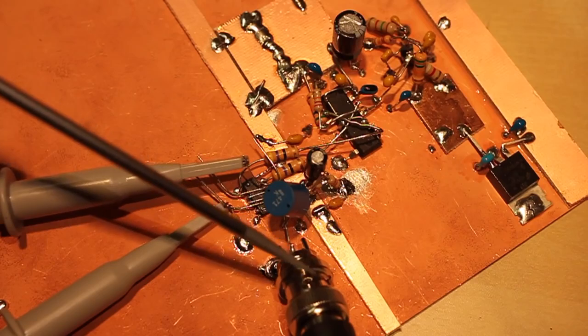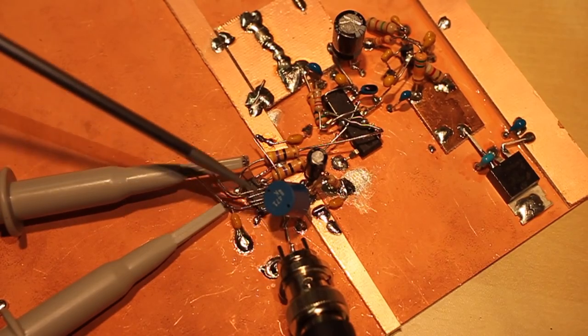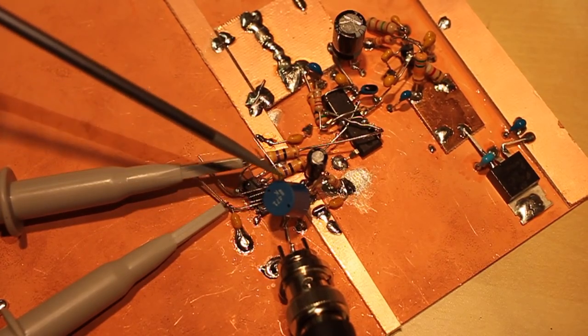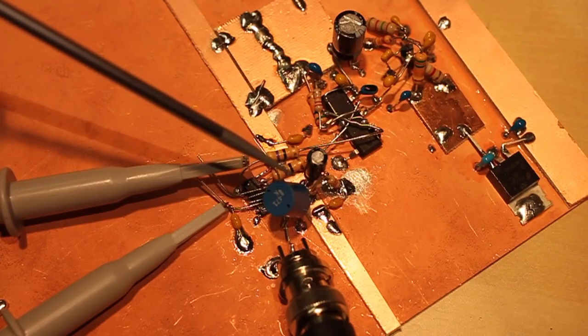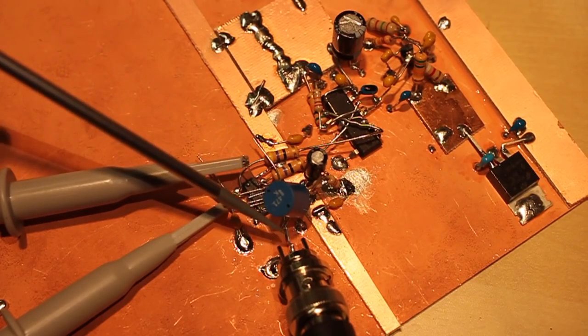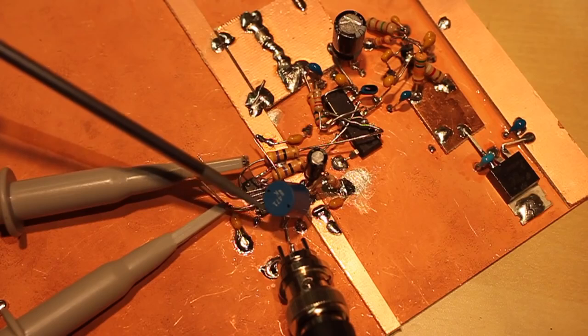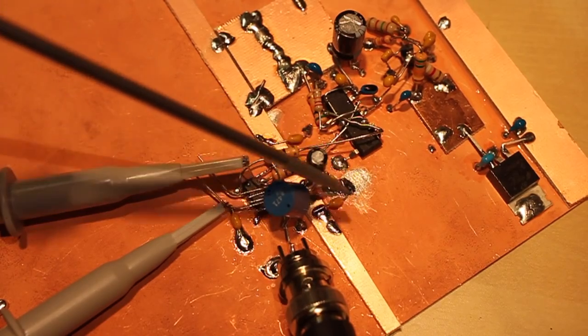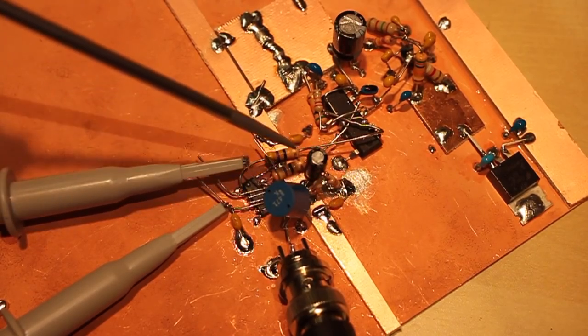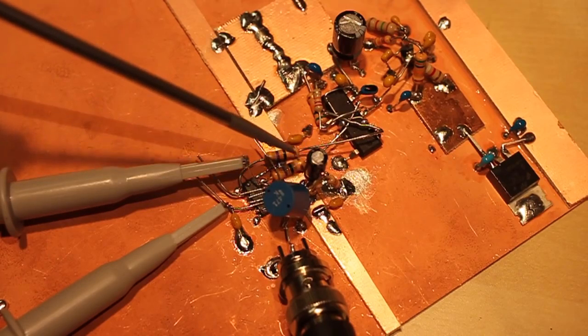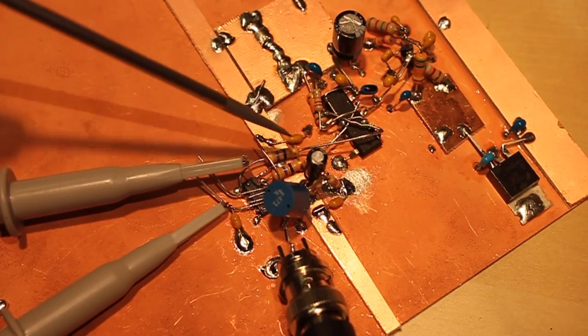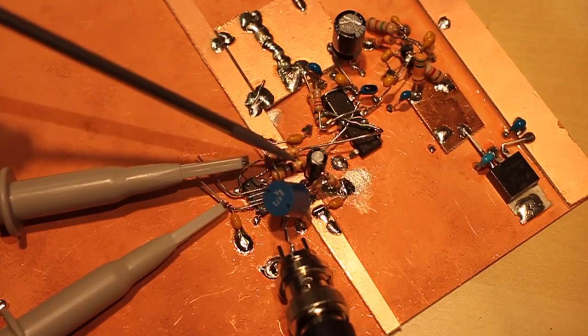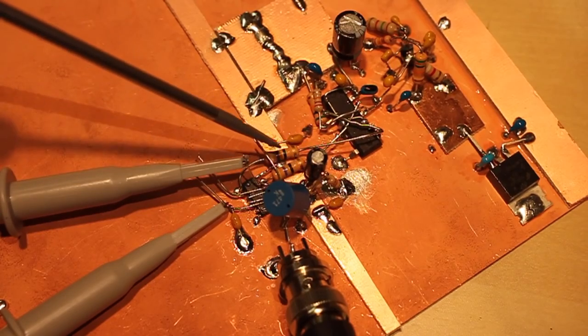And I'm also providing a 7 megahertz signal here to the RF input on the mixer, and we can see I've got that inductor here for setting up the bias on the input for the RF, and a little resistor divider here if you can see it. And I've added some decoupling capacitors here that I didn't show on the schematic, but whenever you're dealing with RF, you definitely want to have some good decoupling there on your power supply lines.